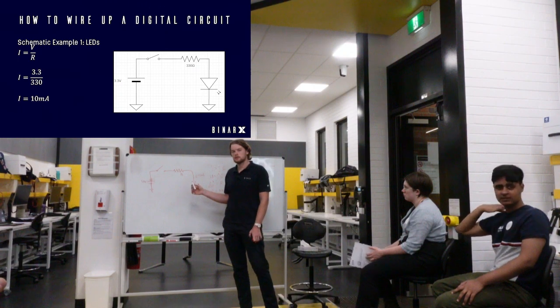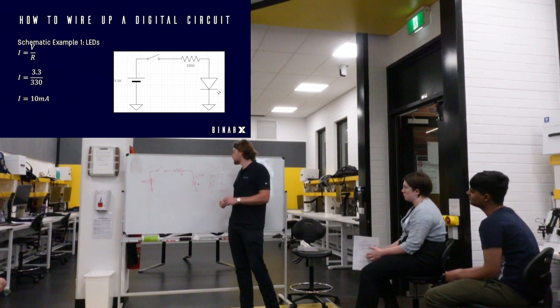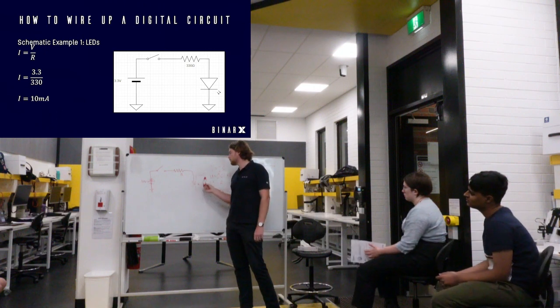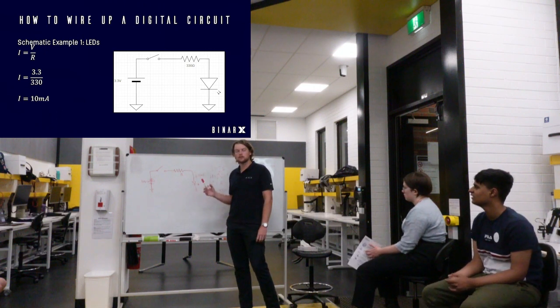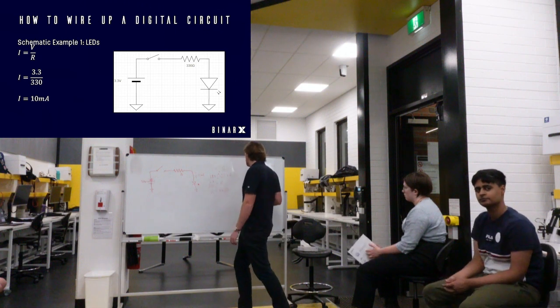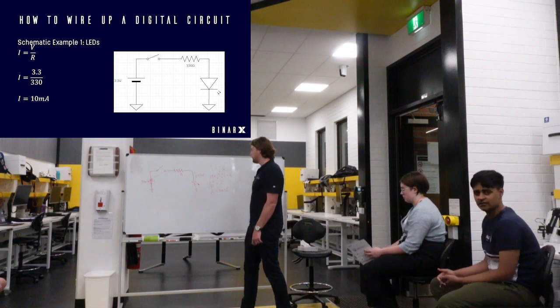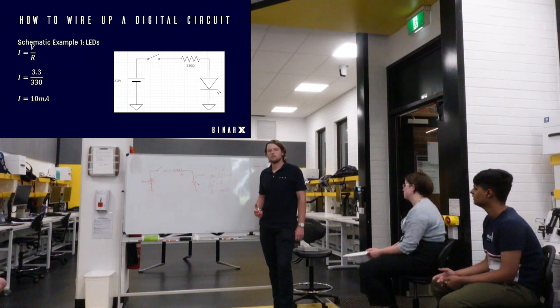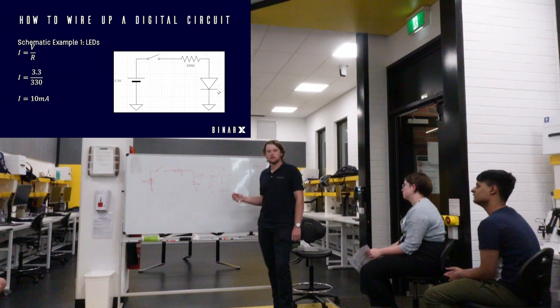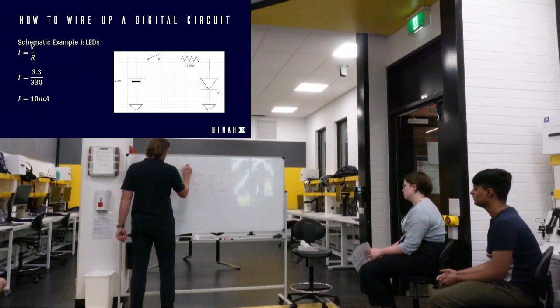Well, we have a few, so one of them is like 1.2 volts. Typically I always just go for the low current value because when you take into account the drop, the current will only rise, right? So this is like the safest value you could use. Do you want me to cover that though? Yeah, if you could show it, because if you subtract the forward voltage drop, then you'll get a new voltage for that one.